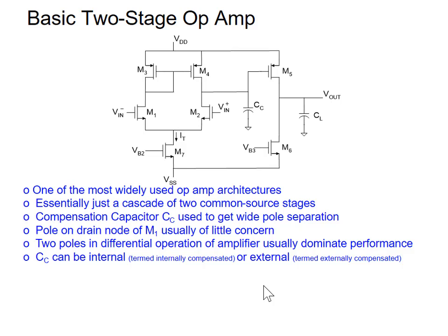Oh, there's one pole I haven't talked about. So we talked about this node here. Ms. Elba correctly identified a concern here. We said that for differential operations, it's not a concern, but there is a node here that affects the difference mode gain. But if you look at the impedances on that node, first of all, this capacitor is probably not too big.